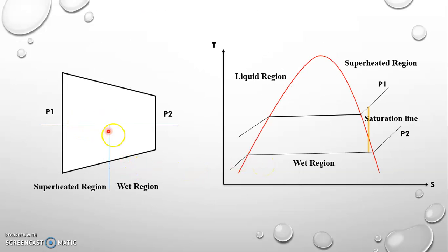In the nozzle, there are two sections: one is a superheated region, the other is a wet region. High pressure steam enters the nozzle. At a particular region, at a particular critical pressure ratio, condensation would start. But practically it is not possible, because the time available is about 0.001 second, so wet steam is not formed. There is no condensation under actual conditions. Automatically, superheated steam is formed at the exit conditions.